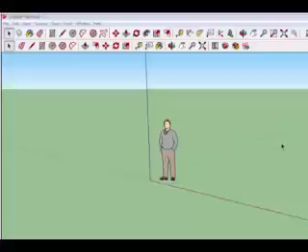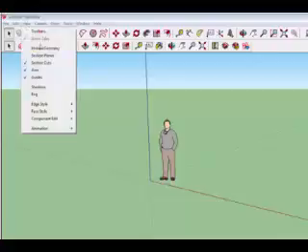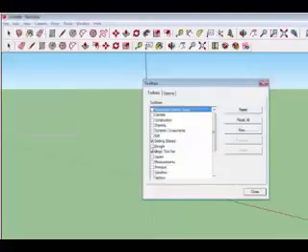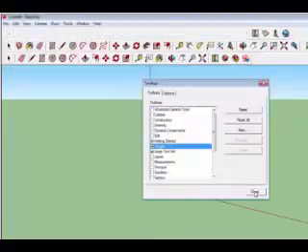Okay, to use SketchUp, here are the basic steps I'm going to show you: how to put on the satellite image of your location, toggle the terrain off and on a little bit, and basically start building on it. First, you open up SketchUp. One thing you will want in the toolbar is the Google set, okay?